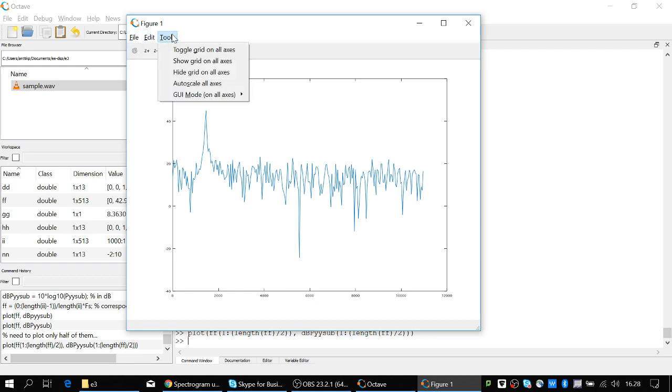Do I have the tool as on Matlab? You can find the exact values, but hey, wait a minute, it shows the coordinates down here on Octave, so it's about 1479 hertz and about 45 decibels. And remember, this has plus minus 43 hertz resolution.